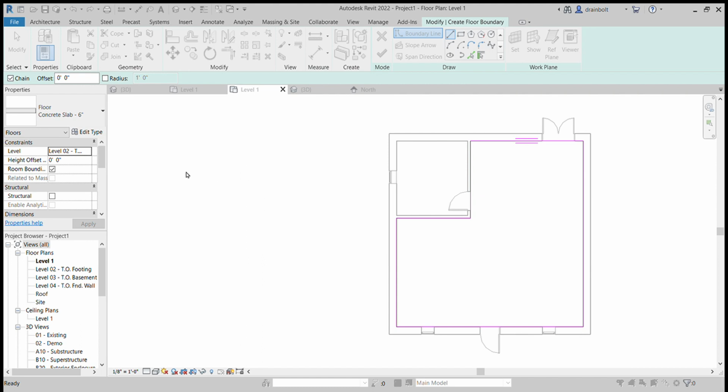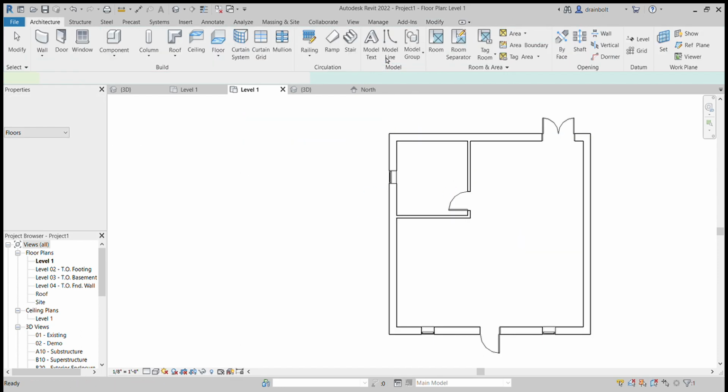And then there are the graphics. If you double click this, you can change the graphics of how this appears for the fill patterns and the drafting. You could go through here and find something. Some of these are specified for certain things though, so you want to be careful with that. But let's just throw in the diagonal down small, and I'm going to click OK. Then I'm going to press the green check mark.